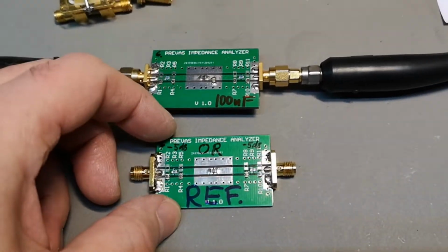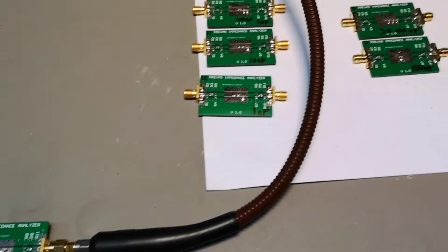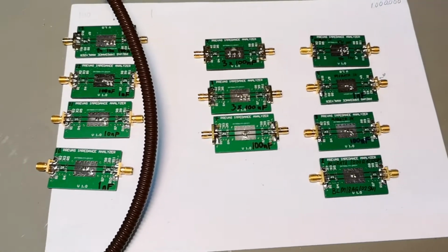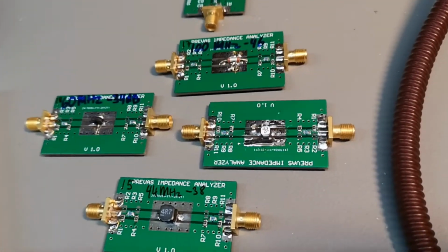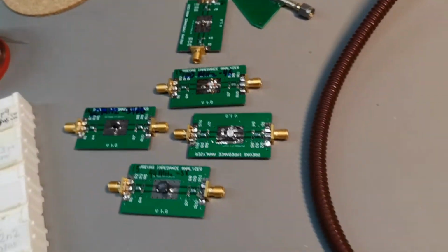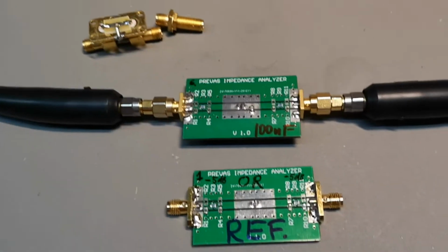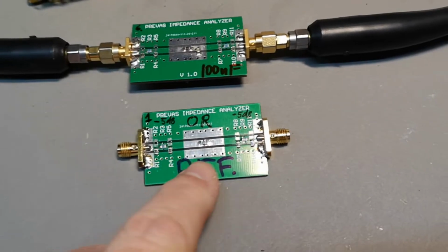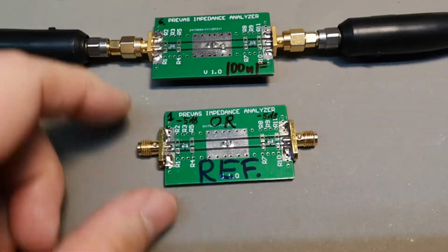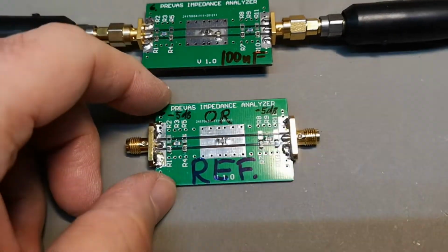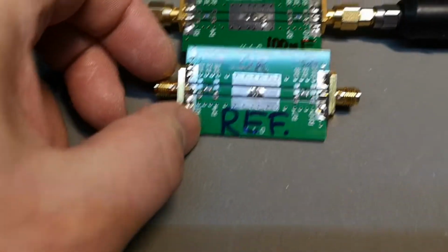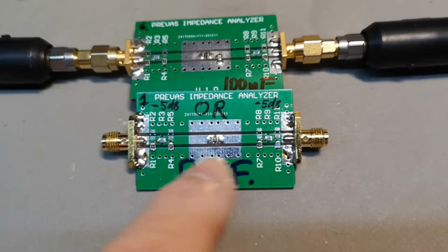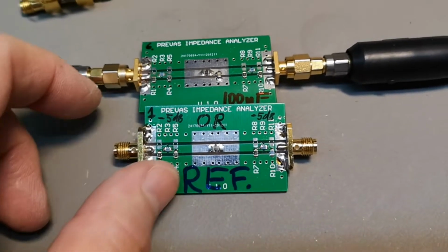Before I did all my tests of all my different test setups, I tested all of them with a 0 ohm resistor and zoomed in greatly, so that I knew that the curve was exactly the same as my reference unit. I'm also using exactly the same resistors from my resistor kit, so that I know that they all perform exactly the same.